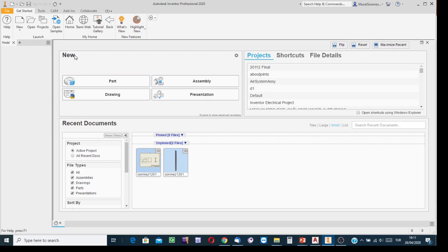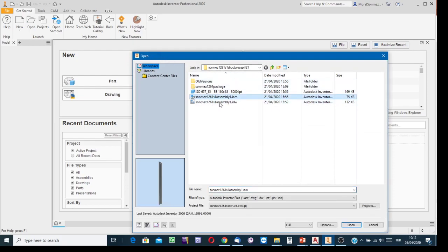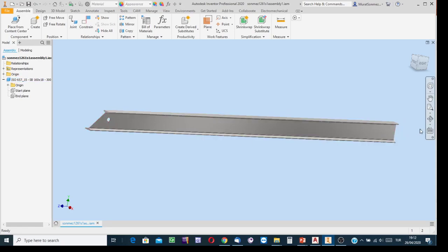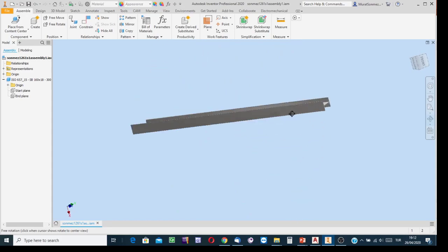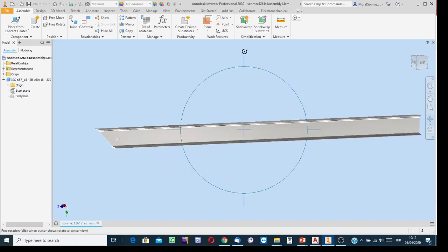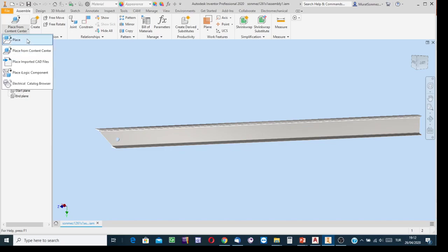Yes. And then to call your memory, on the last part of the session, after finishing the presentation, my delivery about structures and structural elements, remember in the assembly environment, I demonstrated how the model of a standard structural element can be gathered. It is just via invoking it from the library. You know the answer to that question. After bringing the model of the element from the library of Inventor, clicking on this listing arrow and from the list selecting the content center option. I don't want to say the same things.